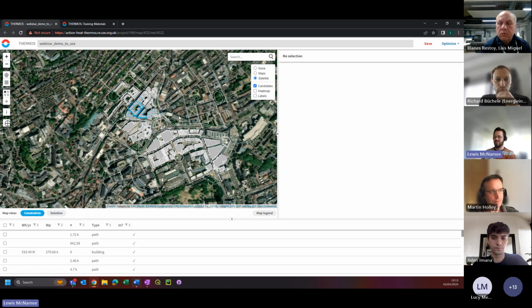So generally in our dealings with UK local authorities, what we're aiming to do is create heat networks that would be available at cheaper or the same rate as gas to the consumers. It's a very important part of UK policy. So that's why I've done that. You can go to the level of detail of setting up an individual tariff for every single building, or you can set it on building types. So like commercial buildings might pay a different tariff to individual residential buildings, for example.